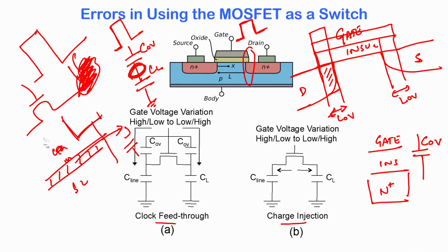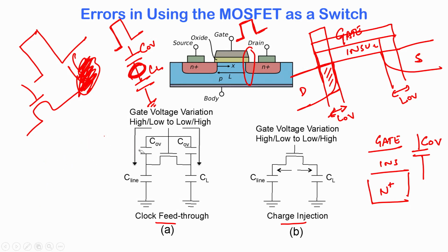So, you now have another mechanism which corrupts the charge stored on the capacitor. So, we had this load capacitor. We already saw that by turning off the gate, this gate transient caused a current through this path, and it created an error on the stored charge in the capacitor.